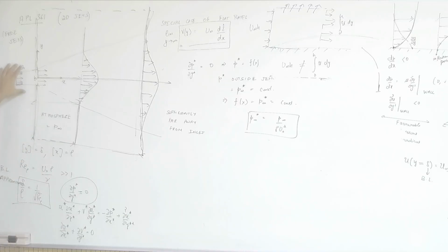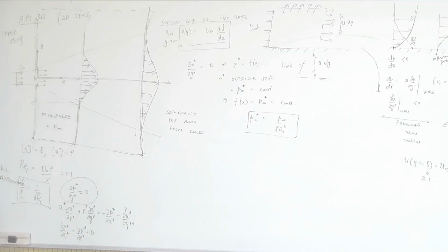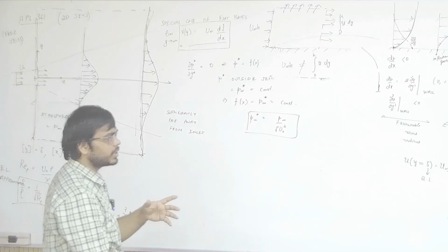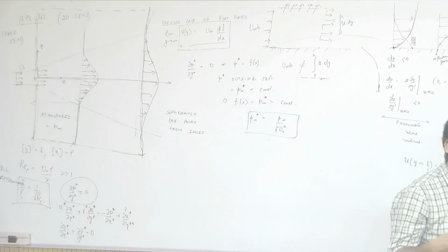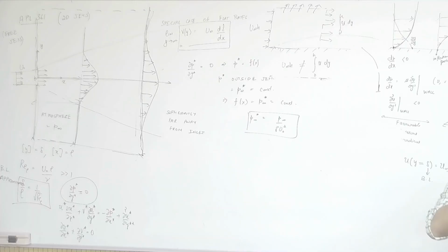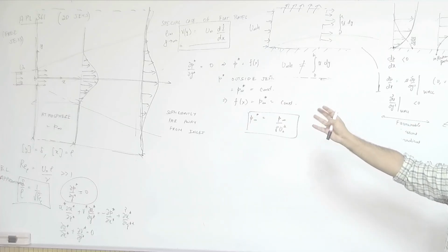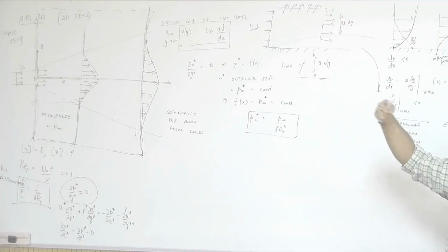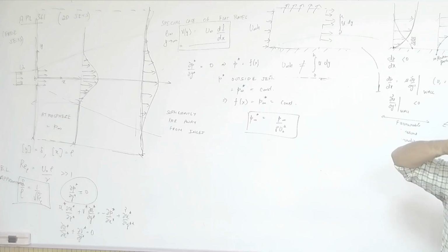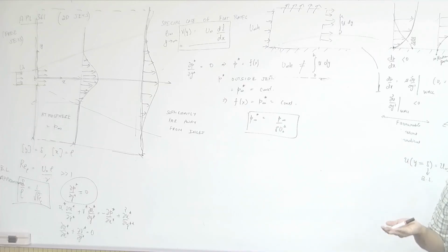Okay, the idea here is that boundary layer theory was first applied to boundary layers where you have a wall and stuff like that, but the approximation of boundary layer theory is actually applicable in other places also, because when you made that boundary layer theory for walls, you made an approximation which you can actually practically reproduce in other cases as well without any particular boundary. Okay. Here you have a flow that is coming out of that orifice into the free atmosphere, and sufficiently far away from that orifice also you can say, oh, my flow is not going to vary too much in x, but it is going to vary faster in y than x.